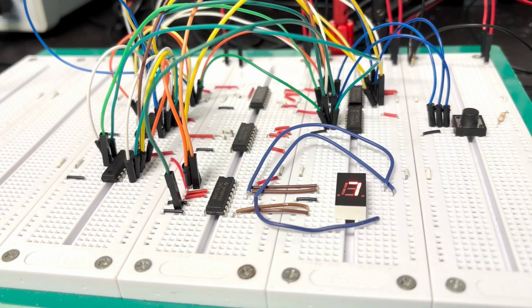This will use the flip-flop's asynchronous preset pins. We can connect these to a momentary active low push button. We can see that once I press the button, it once again follows the state diagram. If there are no asynchronous preset and clear pins, then that flip-flop may not be a good choice for this circuit.